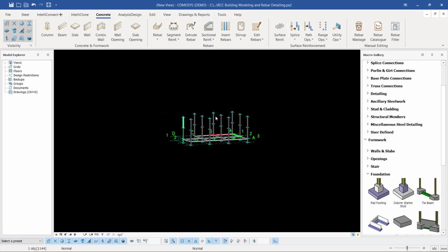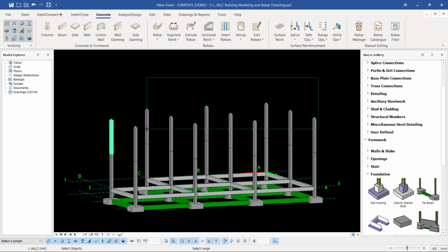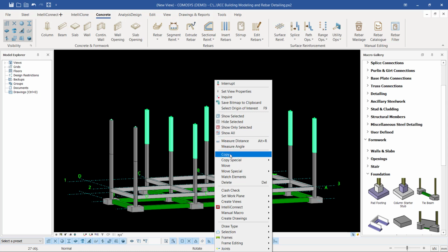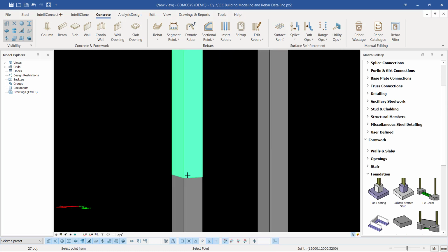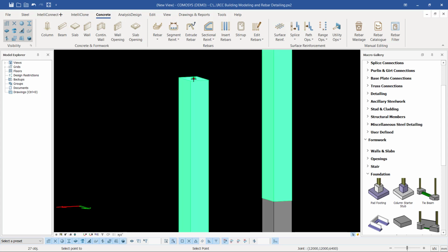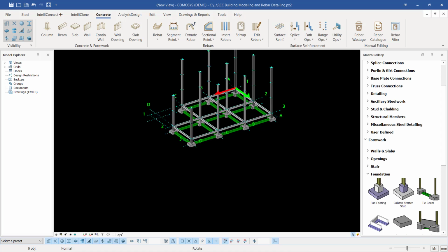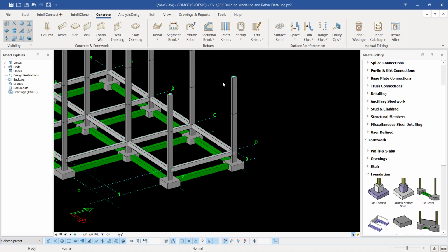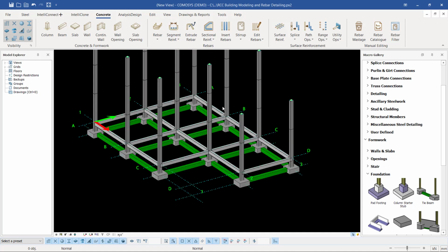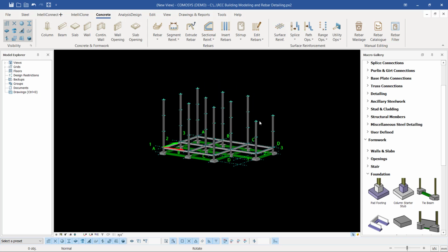I'm going to select everything here like that, right click and come to copy, snap at the bottom end here and move all the way to the top end, because we had readjusted the height of the levels of our floors. The same applies to columns: the heights will also have to match the floor level. I'm going to add another height there. If I right click on empty screen, I'll be able to have that. I've left this because this section will have a staircase. We'll define a staircase here, so I'm going to leave it as it is.